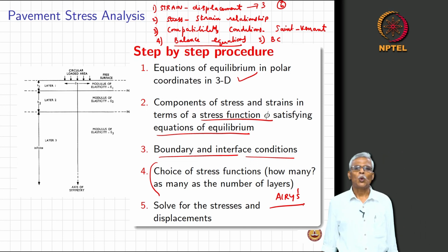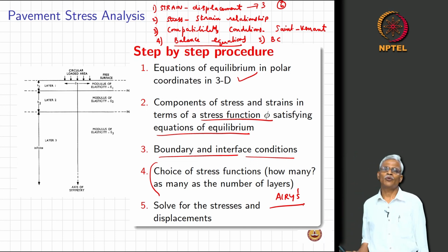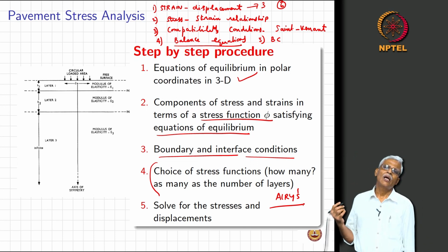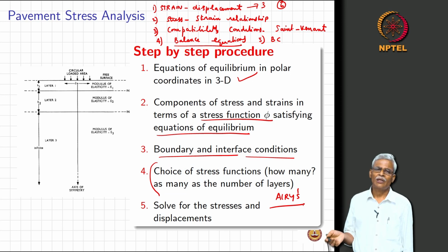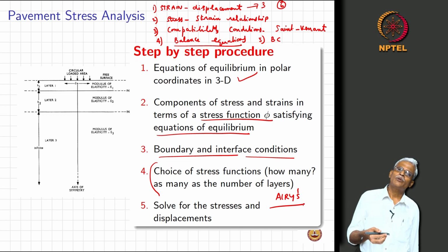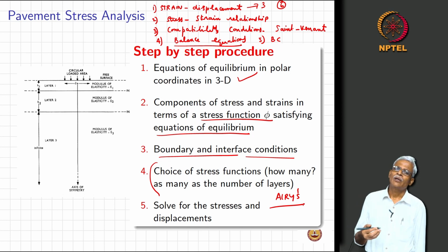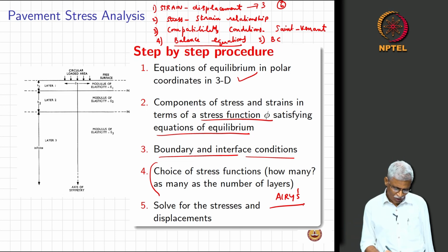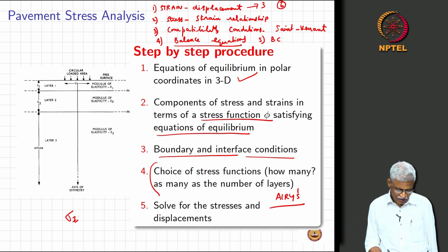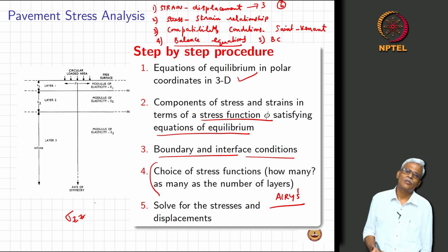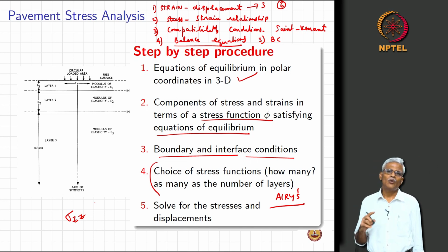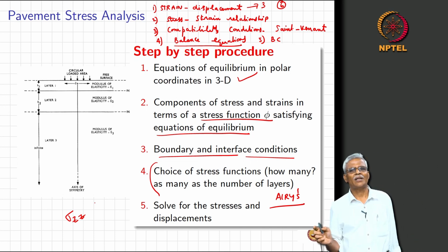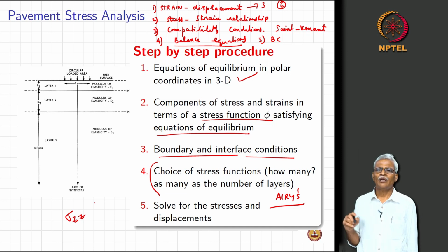So, when you go back, and most of you who have already taken a course in introductory geotechnical engineering, you will be able to see solutions related to Boussinesq. And I would like you to go and take a look at the equation related to sigma zz and watch on the right hand side whether there are any material properties.